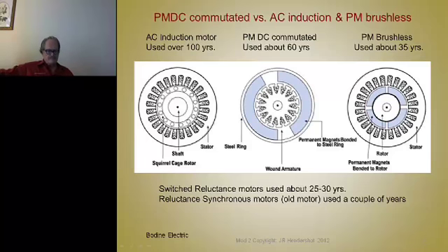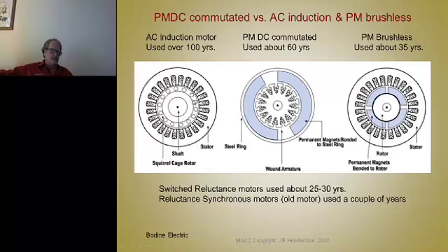And so the current that flows into the stator magnetizes this circuit, and since it's an AC current, if you load this thing down, you're going to get some slip. That means you're going to induce some current to flow into the bars here, which is going to create the right polarity of flux to give you a torque, due to the flux linkage of the ampere turns from this field with the ampere turns from that field.